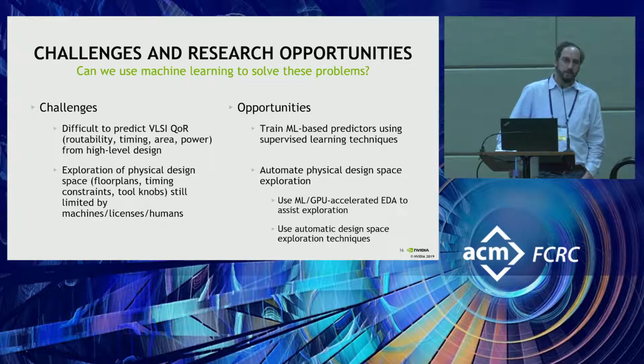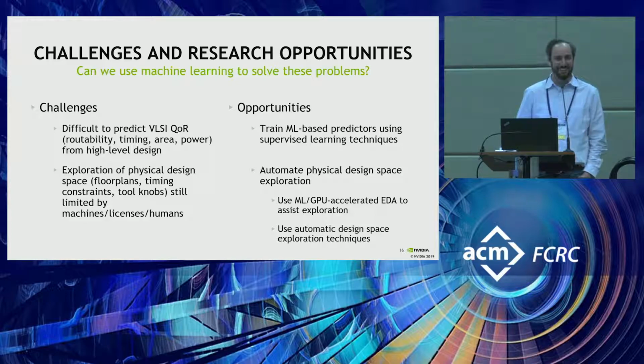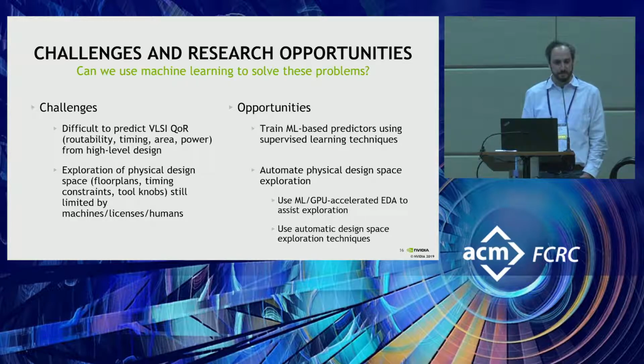Yeah, so there's a question about the readability of the synthesized RTL, which is, I would say, a common issue among all the people that are exploring higher level languages, not just HLS. So there's two aspects to this. I think one is the understandability of the downstream tools. Like if I have to debug some timing path that comes out of my place and route tool, how do I trace that back to some C++ change? So that's a concern.